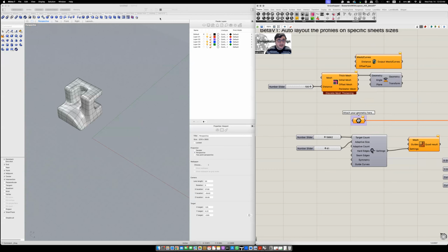Right, now come back to this Bowerbird layout, open it. How you open Grasshopper? Go to Rhino, go to Tools, open Grasshopper. Okay, and then after you open it, you will see this. Open the Bowerbird with layout HIE. That's my initials. Beta 01 with layout. Okay, let's save this one. And you see this attach your geometry here. Right click on it. Select set 1B rep. This one. And this is going to create slices.